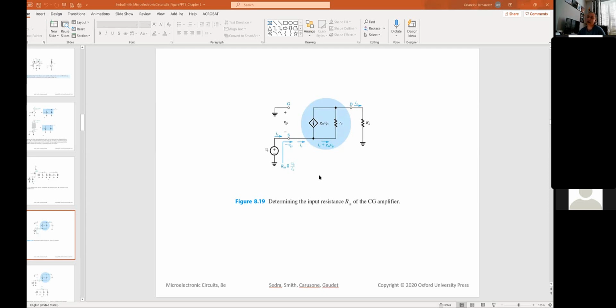And when we go back and calculate the voltage gain, which is the minus gm of the common source amplifier times the parallel combination of the output resistance of the common source itself and whatever it is seeing at that node, at the drain of the common source, that is higher, and we don't get that gain reduction. That's essentially what we're doing.